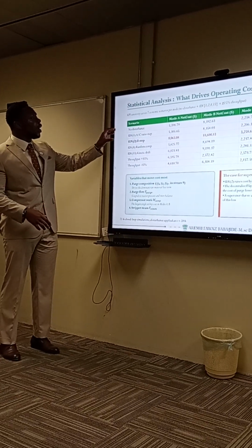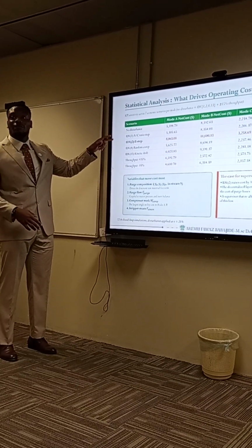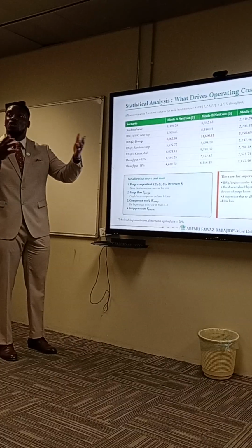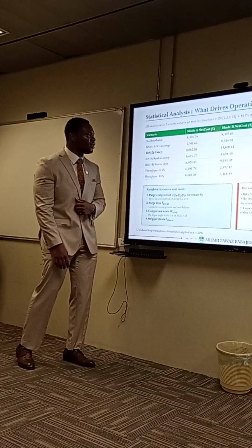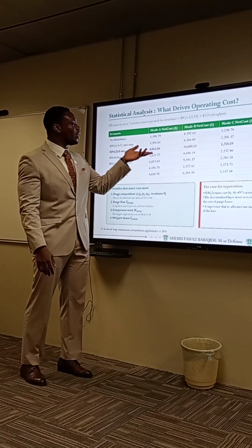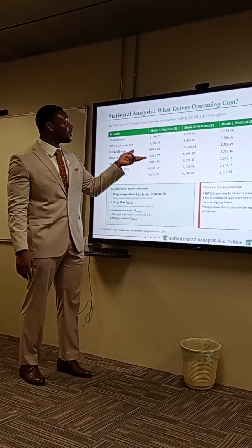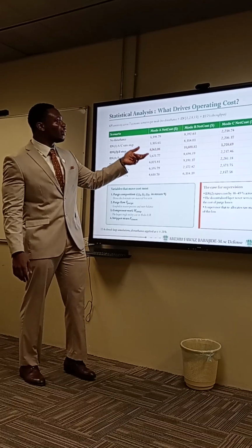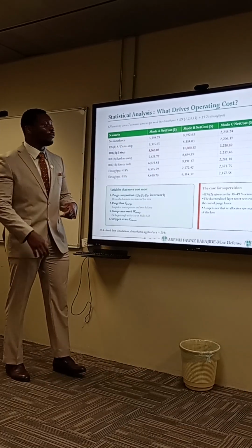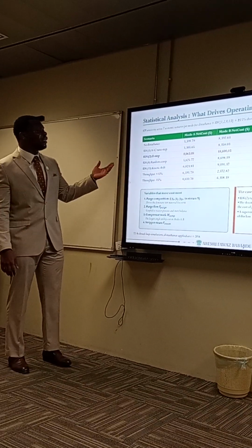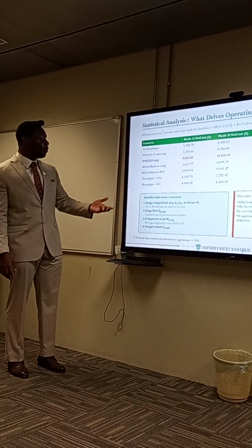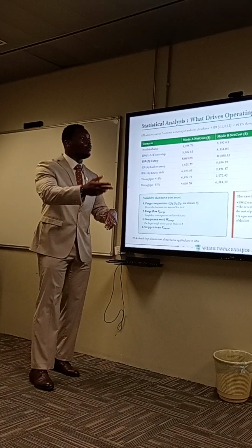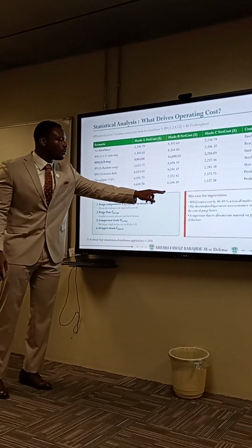Then you can see that when we have a disturbance, particularly IDV2, which is one of Downs and Vogel's disturbances, the cost skyrockets from $5,000 to about $8,000, $11,000 and $3,000 for the different modes. What drives the cost is none other than either the purge composition, the purge flow rate, the compressor work or what have you, based on the cost that we're calculating.